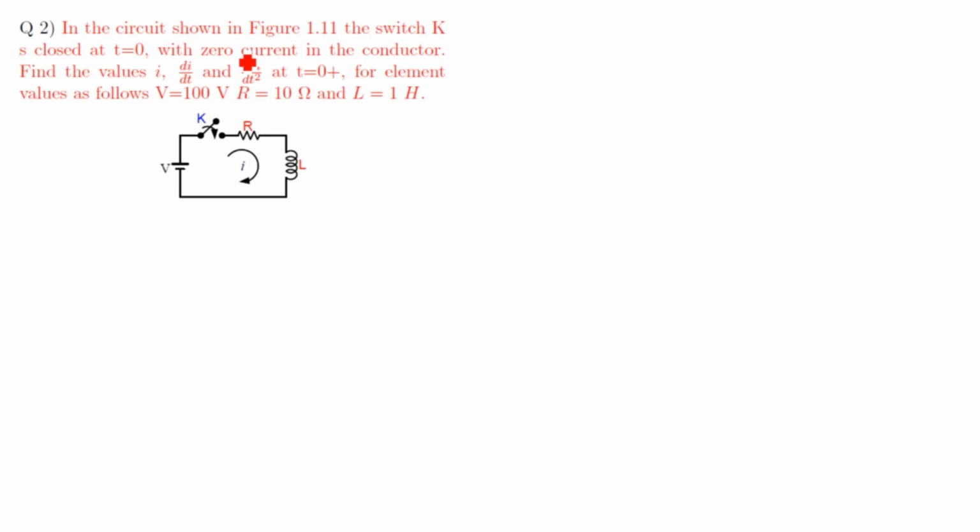Alright. Because of this, there is 0 current in the inductor. That means IL at 0 minus equals 0 amperes. Can I write this as IL at 0 plus?